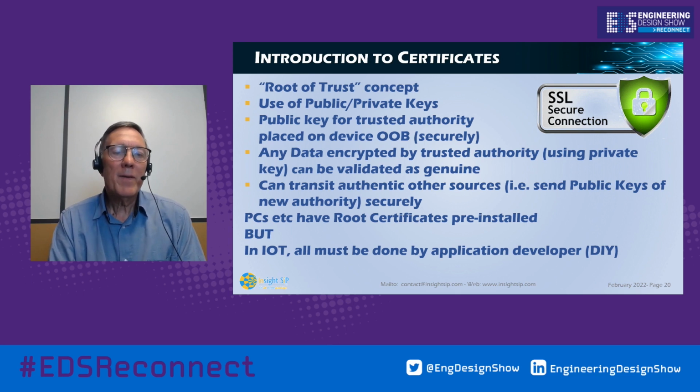Bear in mind, I said this earlier, that PCs all have a load of root certificates pre-installed. If you want to see, just look in the certificates page of your system. But in IoT, it has to be done by hand. If you ever tried to make a Wi-Fi system with a small Wi-Fi module, you'll realize that it's not a piece of cake, and it involves a lot of heartache from the developer's point of view to make sure that they can put the certificates in a secure fashion so that they can't be cheated on.